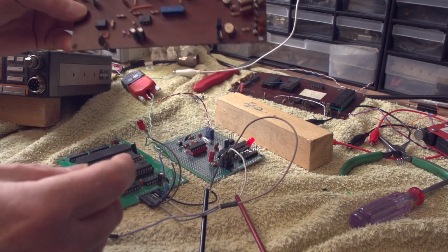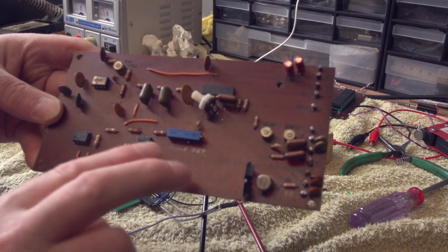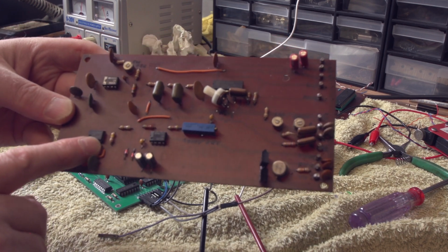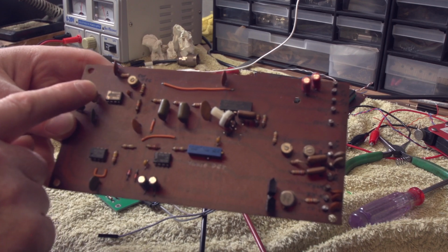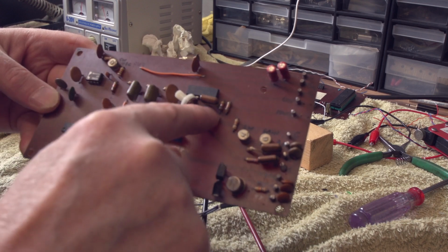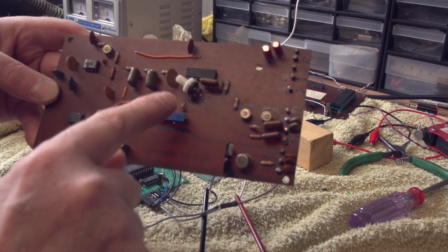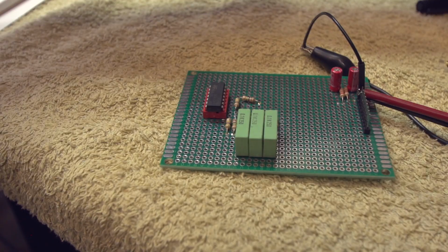So you know, really we're actually doing quite a few changes from the original design. Tone burst circuit's all gone and replaced with the CTCSS decoder. Oscillator is going to be replaced so it can run on a single 5-volt supply, and the 4066 is pretty much the only part that's going to remain the same. So it's quite a few changes to the original design.